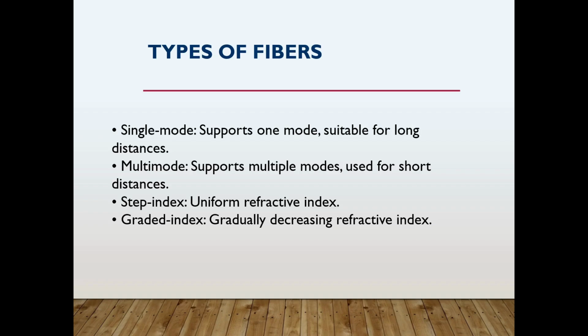To conclude the topic of types of fibers, I would like to say that each type of fiber has its own strengths and limitations. And while selecting the right fiber, we have to keep them in mind. The selection of optical fiber depends on the specific application requirements, such as the distance, the bandwidth, the installation cost, and the environmental conditions.